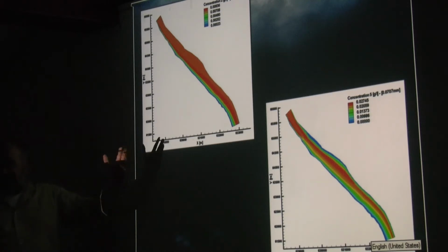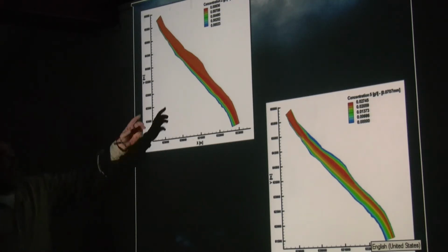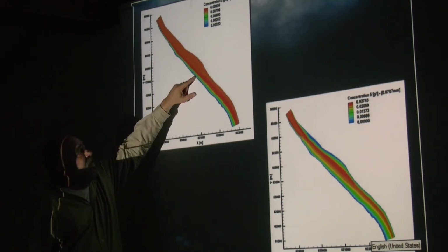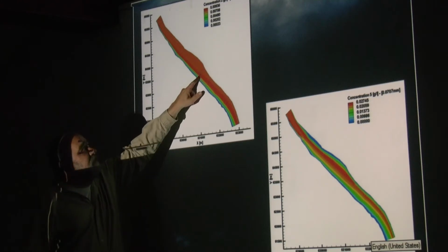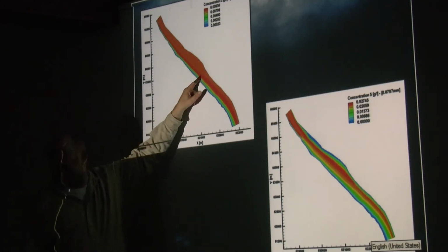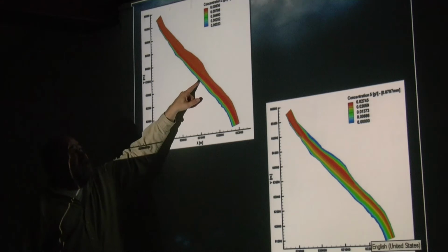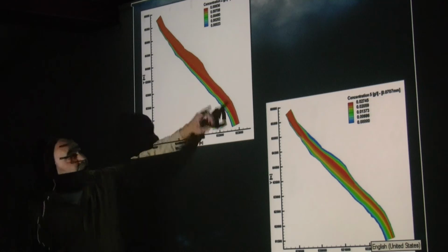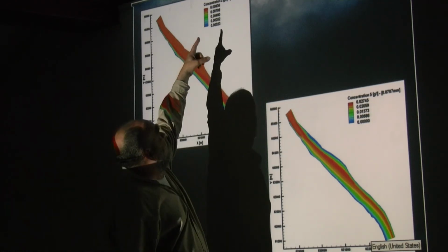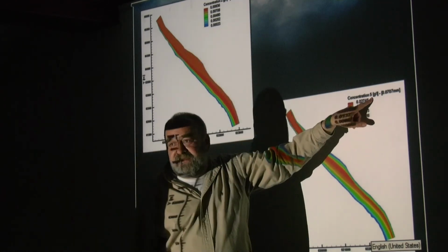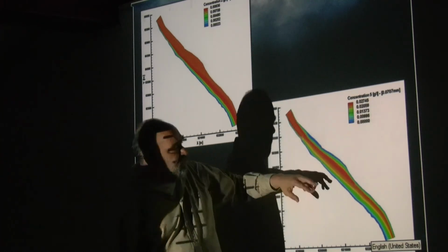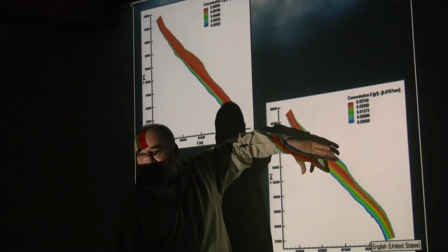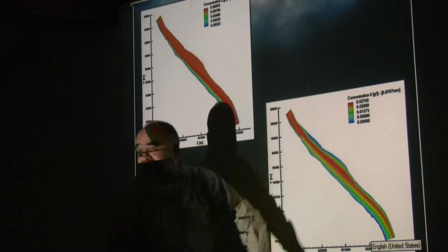These distributions can be related to the flow field. This is a fine concentration, which means that the flow field almost over the entire cross section is strong enough to carry that concentration. Here close to this bank the flow must be low. There is no concentration. This is size class 2. This is the coarser size class 5, which means that the flow is not strong enough to carry it close to both banks. It only carries it in the middle of the river.